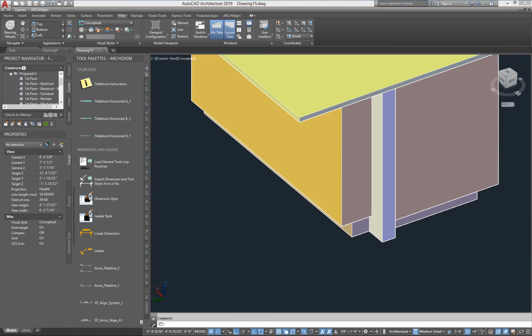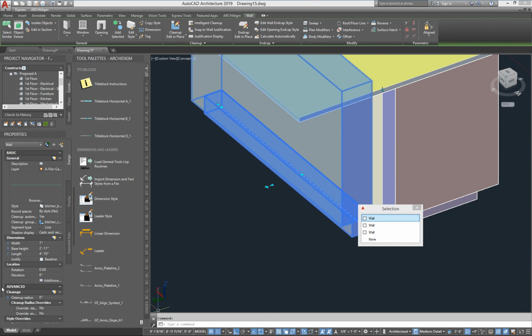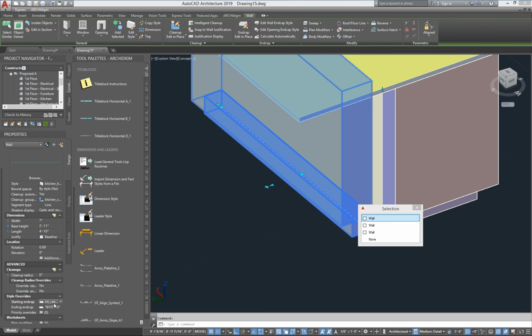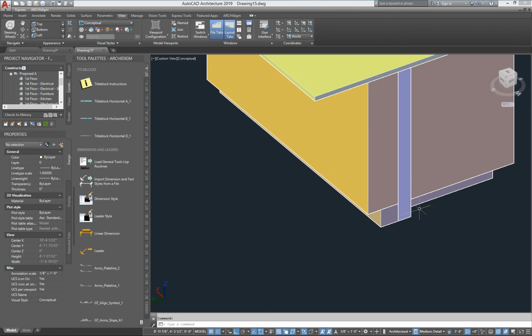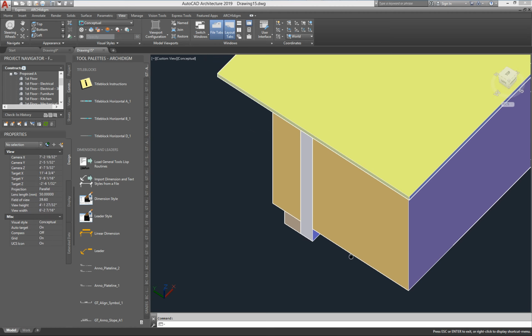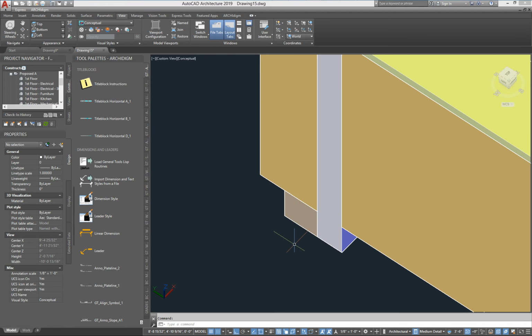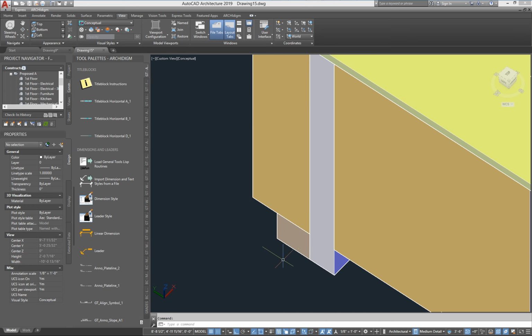So, but this one here, it's not going to work, and we'll have to do a custom wall end cap style. And I've done other videos. I want to set this back to standard. I've done other videos on end caps, but this is basically what you need to do. You draw a P line right here. This will establish your 0, and then you tell it how far out the body above it needs to go. So I'm going to come out 3 inches, then over to here. If I can just get that O track, it's not going to want to do that. So I'm going to turn off this.